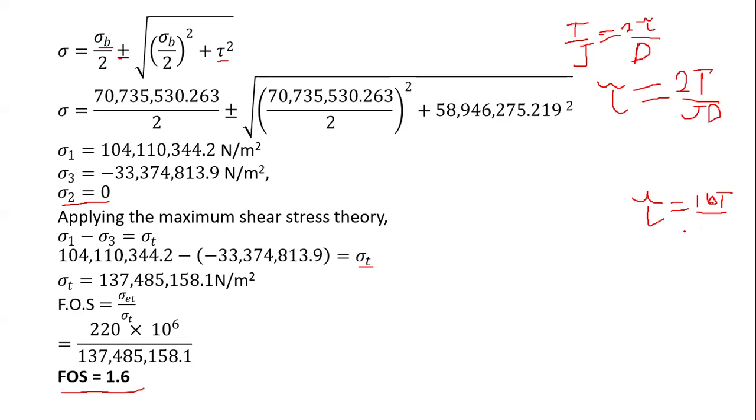So here we're saying that this is pi D^4 over 32. The 32 is on top, then the other one is below. So this will end up giving us, because that's the 32, you multiply it by 2, you have 64. So you have 64T over pi D cubed, or rather pi D raised to power 5, because there's the D here and that's 4. Again, for those of us that enjoy direct formulas, it will still take you to the same result.